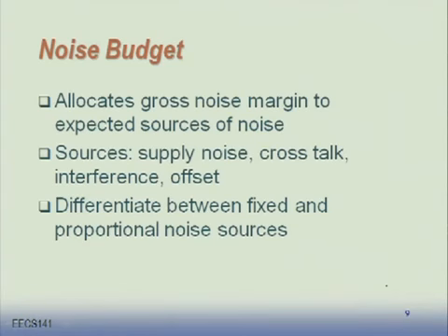We've talked a little bit about the typical decoupling noise. Random telegraph noise is another interesting phenomenon, but for a typical, well-behaved digital circuit it is not that big of an issue. It's an issue for some circuits. Typical places where the noise comes from are the supply voltage or coupling noise from another gate that is switching. We've talked a little bit about that.